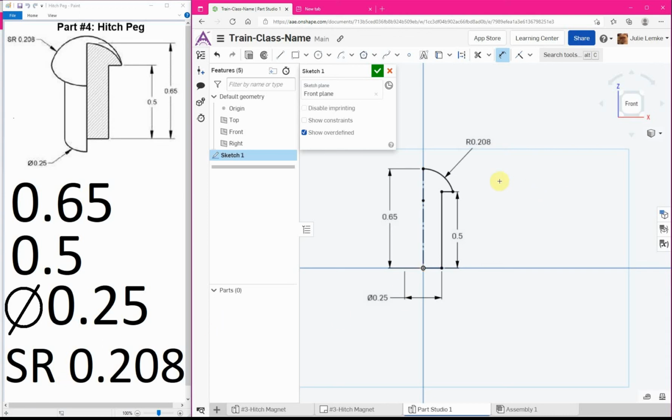All right. So from here, we have everything all dimensioned properly. I'm going to back out of my dimension tool. Now I'm going to click on that starting line again, and then click on the construction line tool. So that's undoing that construction line. So you see how it went from the clear kind of background color to a little bit of a gray. That shows you that we now have a solid shape to extrude or revolve or whatever we want to do. Before it was kind of like open, even though it had the line, construction line from when you're extruding or revolving, it ignores it. So that's why we had to undo that little piece.